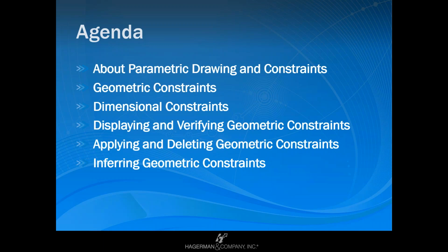So we're going to talk about what constraints in a parametric drawing are. I'm going to demonstrate geometric constraints, dimensional constraints, how they're displayed, applying them, and then having them on all the time, which is inferring geometric constraints.